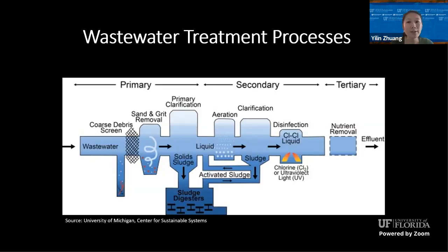Secondary treatment is a biological process. It is used to stabilize the dissolved solids. Microorganisms such as bacteria feed on organic solids in wastewater and convert the organics into biological mass that can later be removed. These biological processes are aerobic. Oxygen must be provided for these aerobic organisms to work properly and efficiently. An integral part of secondary treatment processes is another set of settling tanks.